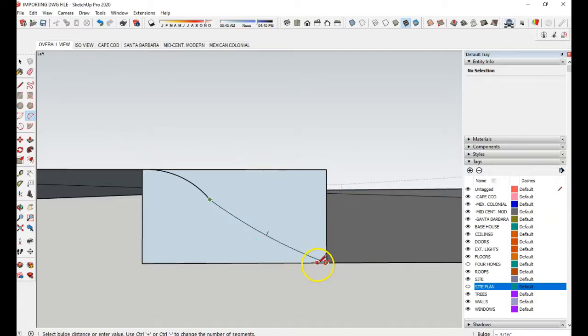And then, oops, I forgot to stay there. So you got to get it back to where it looks like this. It'll jump around a little bit, so you got to be careful right there. So when you see tangent at vertex and you see the cyan color line, that's when you should pick. So when I pick there, again, that means that we have a nice transition between these two arcs, and we don't have a bump here or an angle. And something generally like this is fine. It may look a little different, but you should not have an angle right there.